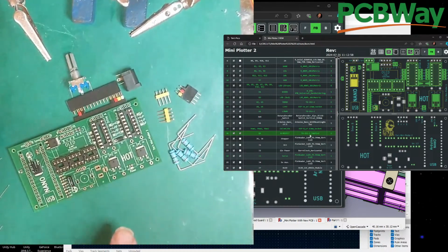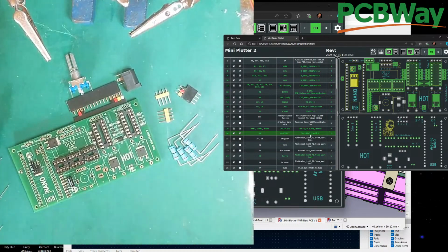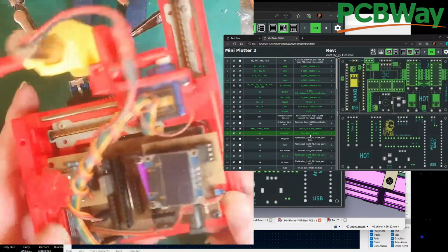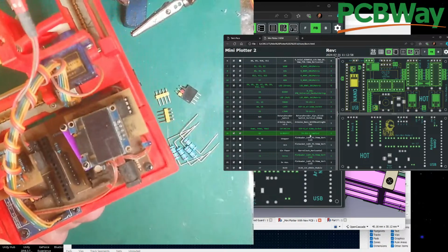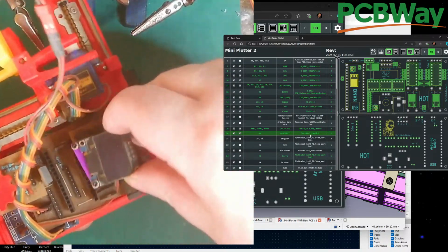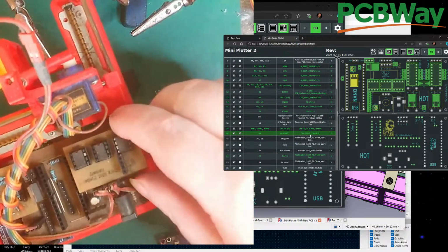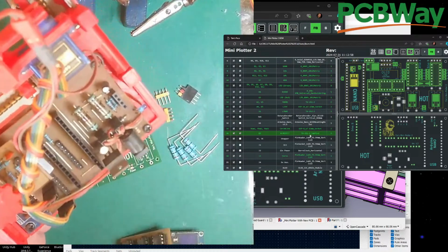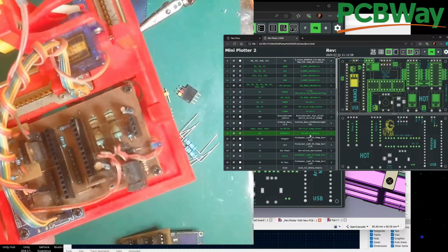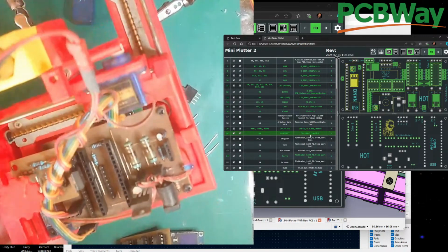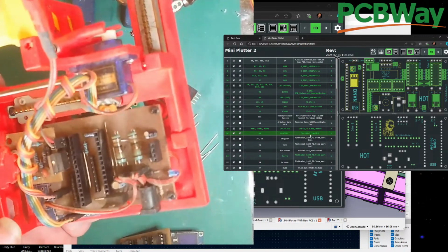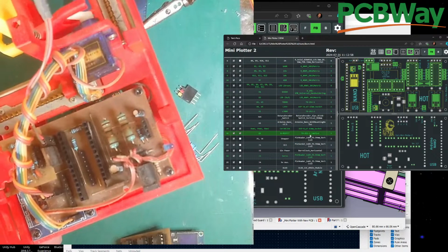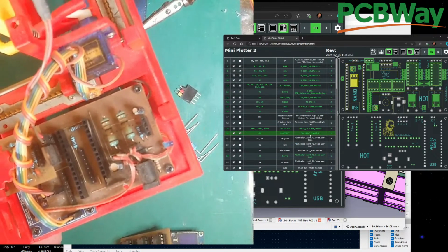On the previous videos, I was going to show you what happened to them. Well, before I forget again, you know my memory. So on my old one, have I got it in shot? Right, yeah. On my old one, so there's me LCD that sticks on me OLED. And then there's my memory on top of my thing. But then can we see them resistors? Can you see how they're a bit charred? I mean, the colour hasn't gone from the bands yet, but with some use they're getting a bit charred. So there were 2 watt resistors.